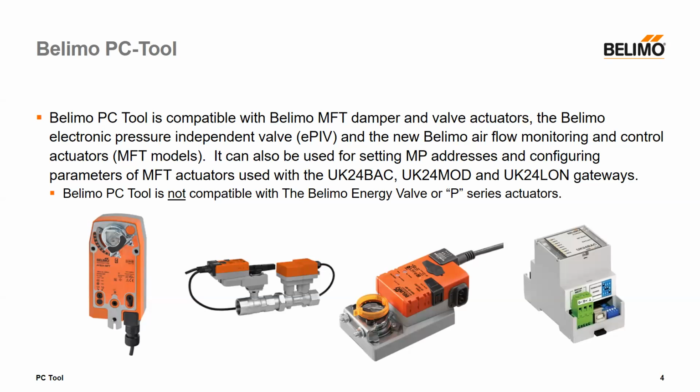So the main focus of PC Tool was based around the Belimo MFT actuators. So if you buy a Belimo airside damper actuator, you may see an AFB 24-MFT, or you may see a similar actuator like that on a control valve. So any MFT actuator that is either a damper actuator or installed on a control valve is applicable to using Belimo PC Tool. It also works with our electronic pressure independent valves, the EPIV.